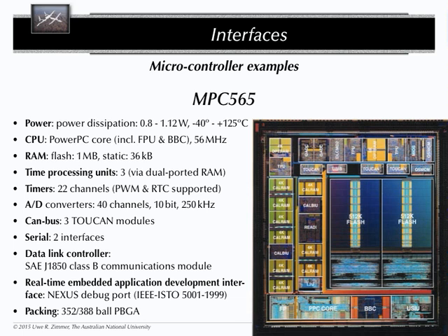And you can have CPUs which are fast enough to do that because they're not clocked at gigahertz, they're clocked at a few hundred megahertz. So you need to have something which can interpret it on the other side fast enough. You can also change register values. You can get information when a specific memory address has been triggered, for example. You set traps into this debugging environment, just like you used to in a GDB environment, only that this thing is actually running live at the same time, which is pretty cool.